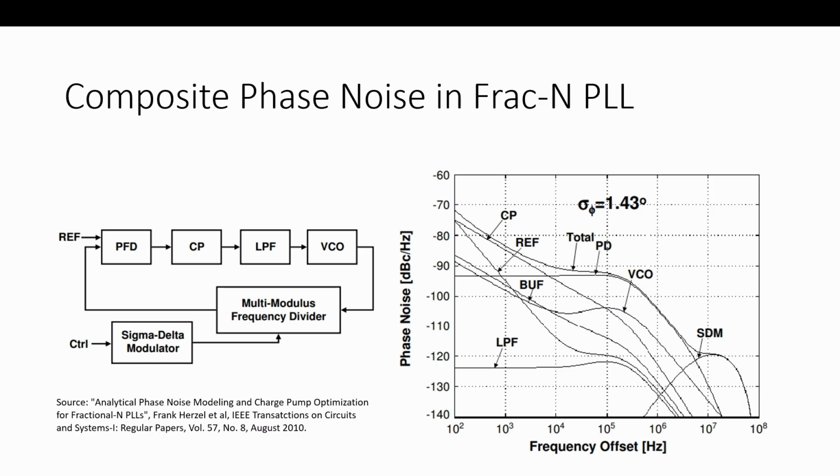So they're a result of a bunch of two-port transfer functions. Every one of those inputs could be outputs. And that's a different forward gain. What's the forward gain from this node into the loop to the output? We can do that with the loop model that we described. That makes sense? The important takeaway is how practical having the loop model early on is in terms of specifying what each of these components need to be in terms of their noise performance and stuff like that for a target response that we may describe in frequency, such as this is the composite phase noise.